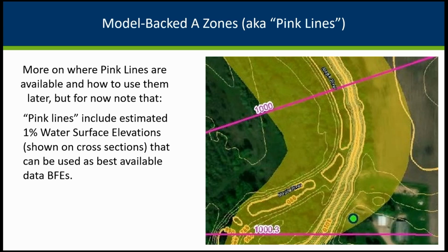On that viewer Lake and Flood Elevations line, we show those lines as pink, so we refer to them as pink lines. I'm going through here. So you can see here, these two cross sections, the one elevation there was right at 1,000 feet. The other one just upstream to the south is 1,000.3 feet for that particular one.